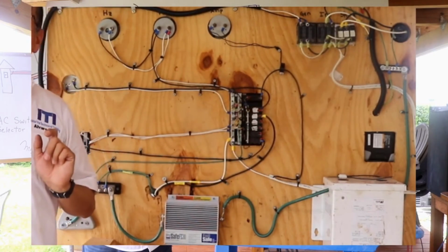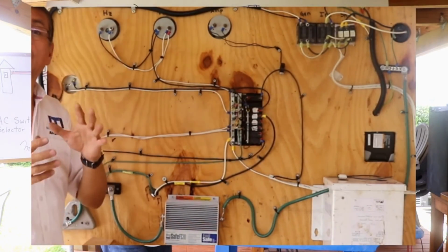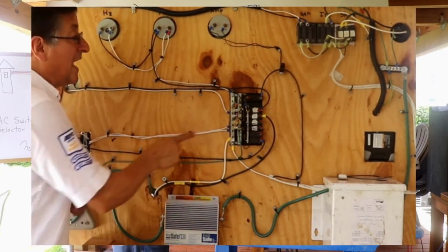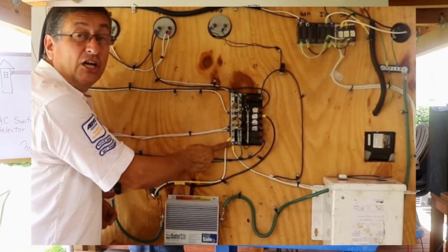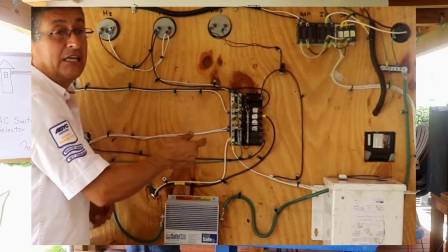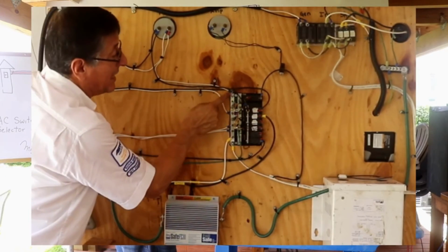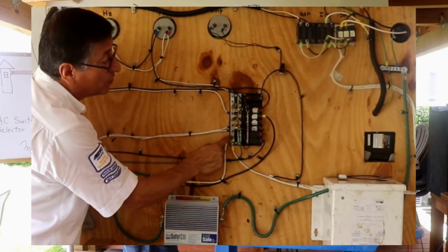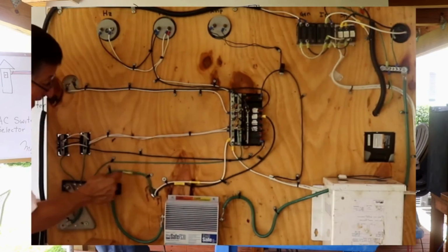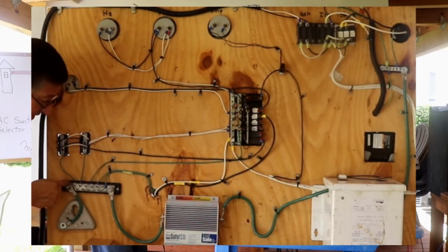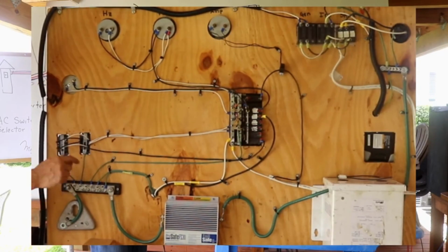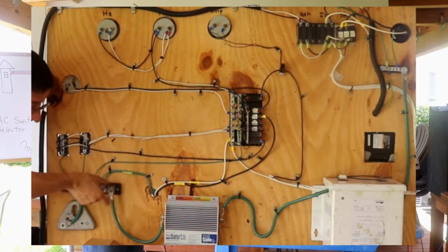Never put them together. If somebody enters the boat and installs other equipment and connects this with this, and this one right now is hot, it's catastrophic. If this one right now is hot, and you suddenly connect the neutral with the ground, the bonding is hot, 120. Remember, what equipment is connected to the bonding system, to the bonding bus bar?